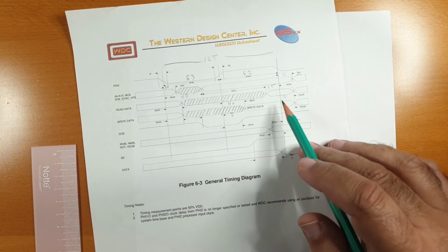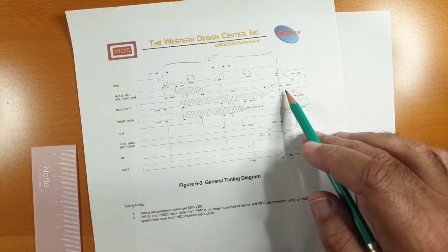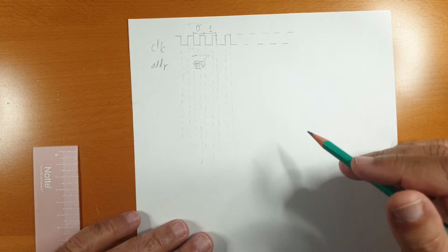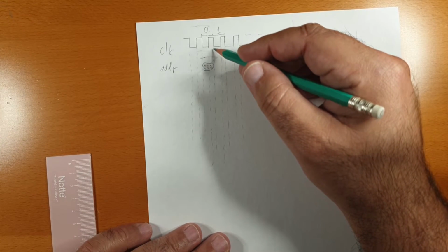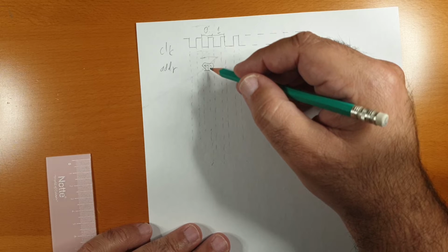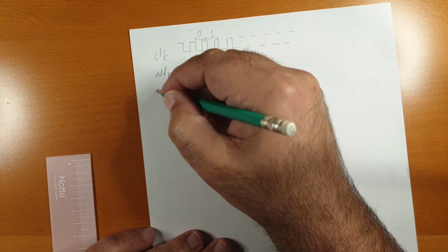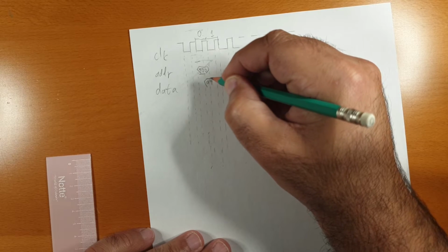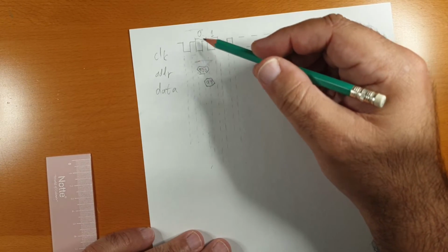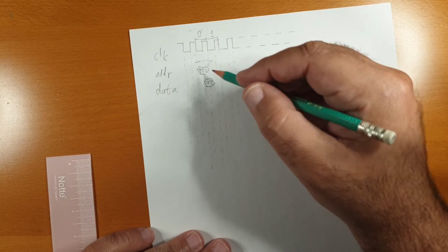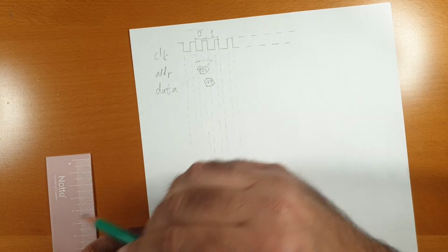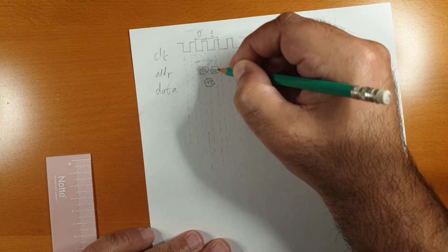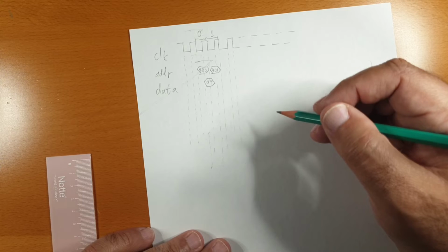Now, you'll notice that the data is only valid for 15 nanoseconds before the falling edge of the clock and 10 nanoseconds after the falling edge of the clock. So it is only available a little before and a little after this falling edge of the clock where the 400 address was given. So our data line will say A9 and will be invalid the rest of the time. During the second cycle of the command, the address will read from the next byte over to read the immediate value. So this area will be 401. Let's assume the value we're loading into the accumulator will be D9.